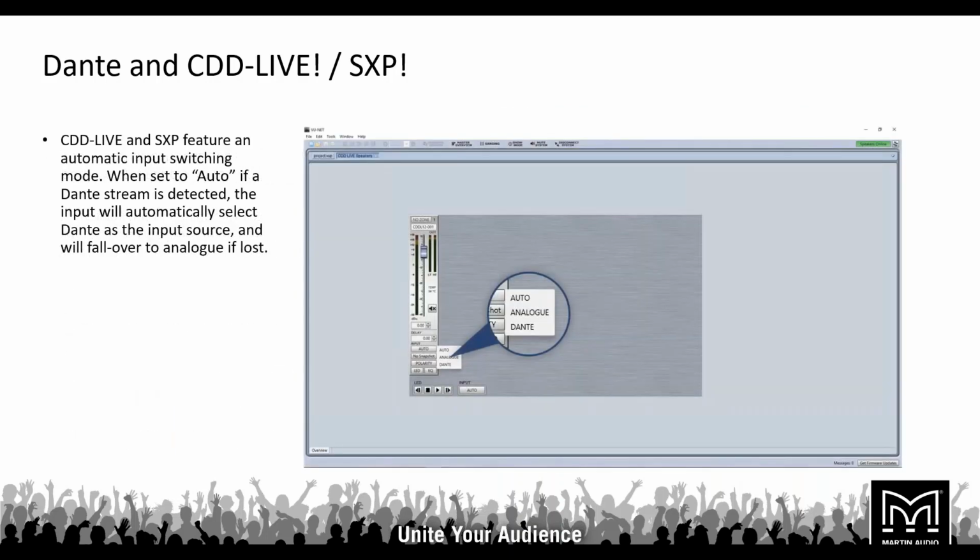So double clicking on our CDD-LIVE product will bring up all of the CDD-LIVE that we have included within our project here. And what we can do is change the input source just by selecting where it says input underneath the delay parameters and choosing analog or Dante. By default, it's set to auto. So there's a hierarchy here in that if Dante audio is present, this will be the primary input source. However, if we lose the Dante audio and we have analog also connected, it will fall over to analog.